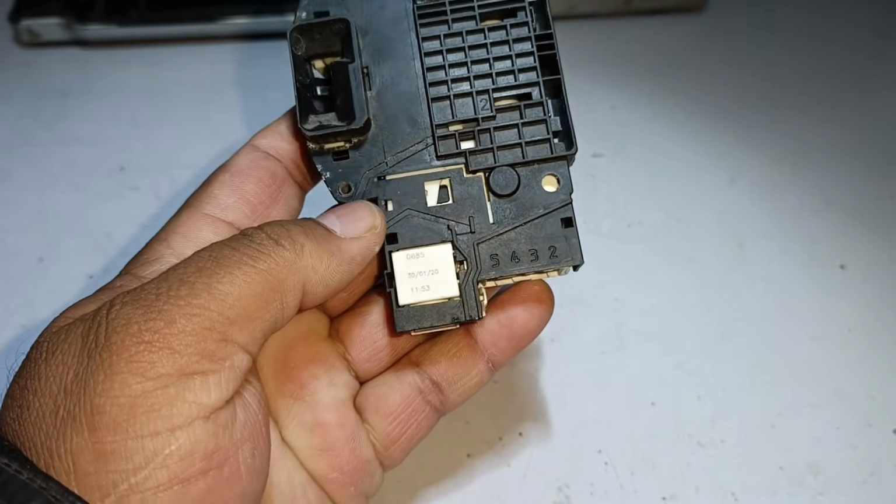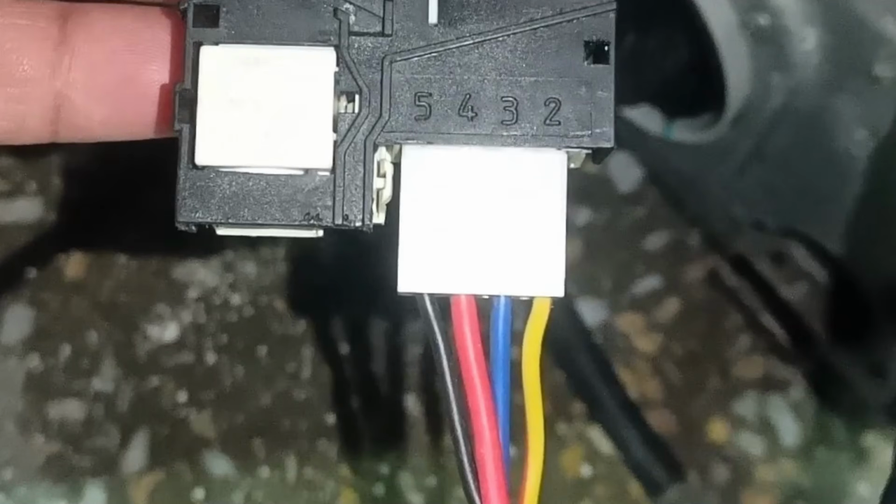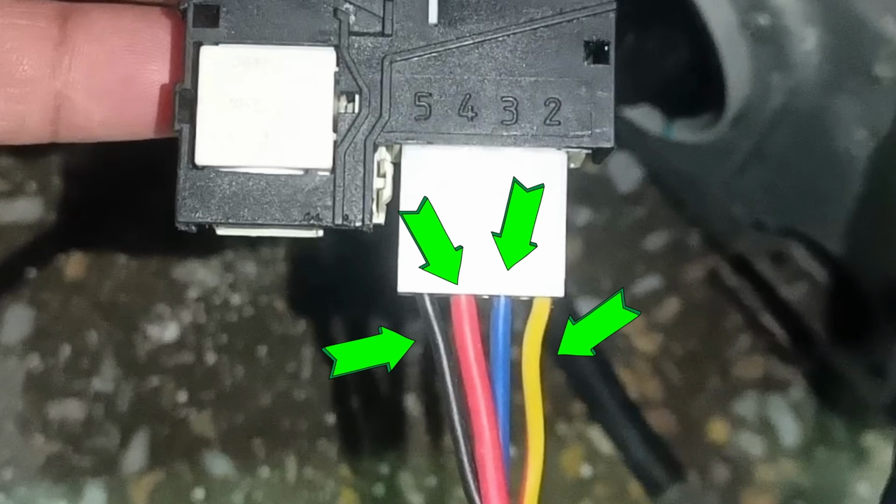But if the electricity goes off, the supply is completely cut and it will not open until the power comes back again. Now, if we look at the wire color code for this door lock, yellow wire is the neutral, blue wire is the input signal, red wire is the line, phase, black wire is the output signal. This color coding helps us identify and trace each connection correctly.